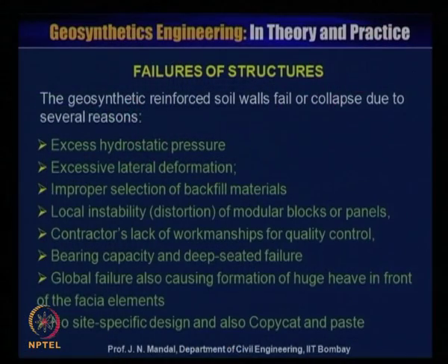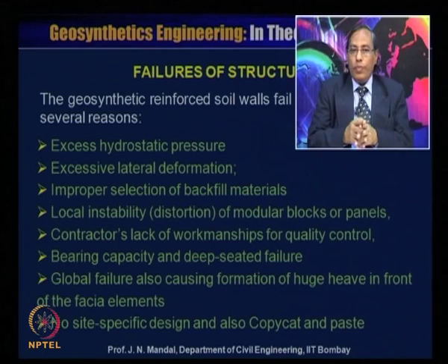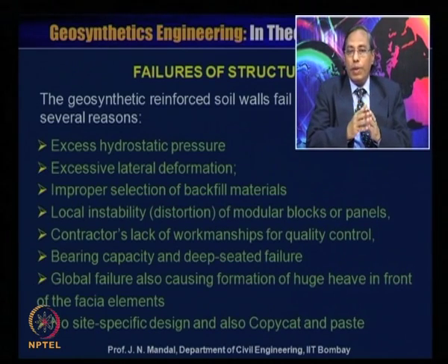Now, failure of the structure. The geosynthetic reinforced soil wall may fail or collapse due to several reasons: excess hydrostatic pressure, excessive lateral deformation, improper selection of the backfill material. So, you have to be careful in the selection of the backfill material. You should follow the specification and gradation of the material.